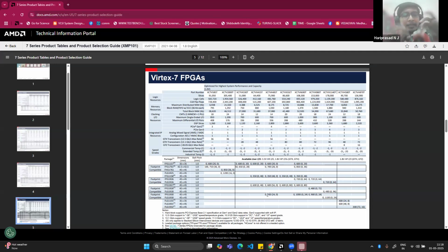So we have to take care of these kinds of scenarios, especially if you are deploying your device in the Navy, where there will be a lot of saline environment and your device will start degrading, whatever the components are. So we usually do something called a saline test. We keep the device in a saline chamber for maybe 2 to 3 weeks, and we see how your device responds.